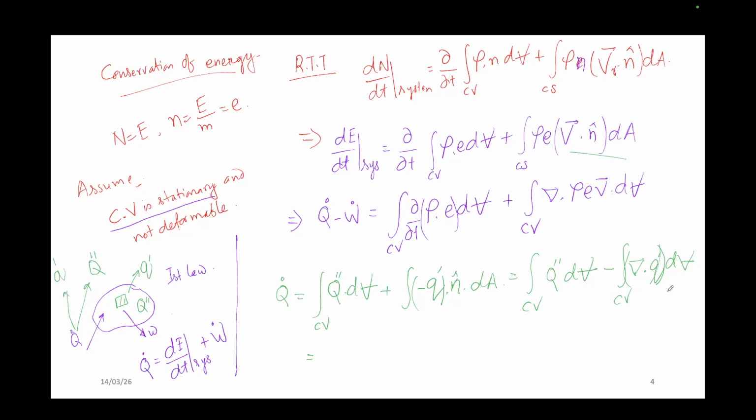Okay. So this term is in the control volume. Again we have got the Q in the control volume term, right? Similarly, if I talk about the work, what is the work? Work also consists of two terms: the surface work done, and the body work done because of the body force. Surface force is basically the shear term we have talked about in the earlier classes.